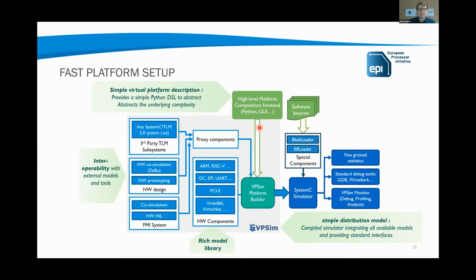Once the user has set up a platform using the high-level Python interface, VPSim will simulate the behavior of the platform by leveraging the SystemC simulator and produce fine-grained statistics and debugging information. So you can use GDB to develop software on top of VPSim for more efficient software development ahead of the availability of the circuit. And we can also provide some efficient statistics and monitoring features to the user.